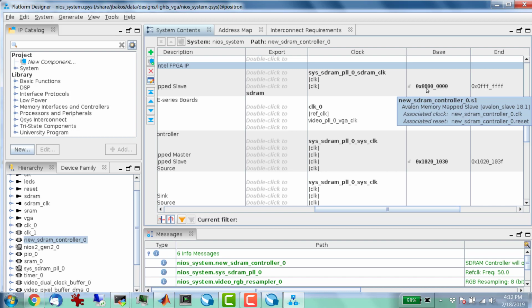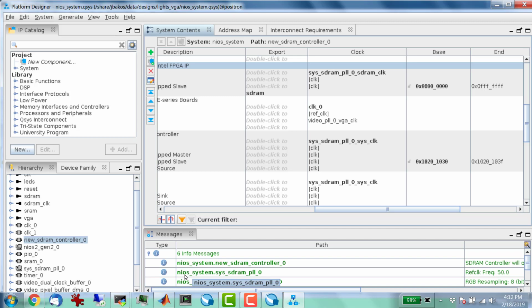The reason I'm pointing this out is because I've made this mistake many times where I updated addresses in the platform tool, and I forgot to update the BSP. And so when I went to load in the debugger, it loaded at the wrong address because the address had changed. Of course, you could solve this by just locking the address. There's a little lock thing here. You can lock that down. It's probably a good idea. Does that make sense? You guys all with me on that? Okay.